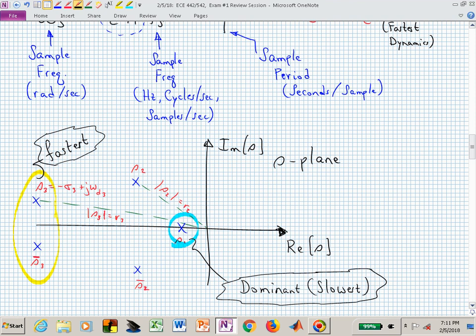And I'm trying to also give you a little bit more insight. S sub 1 is the pole in the S-plane that's closest to the origin. That's actually the slowest pole. That will dominate, so that exponentially decays much more slowly than the poles at S sub 2 or the poles at S sub 3, just because of their comparative distance into the complex S-plane, their real component.